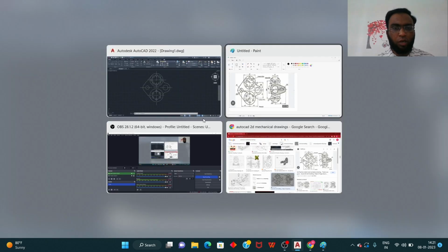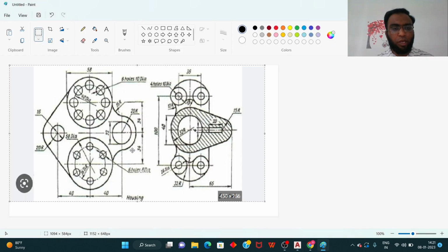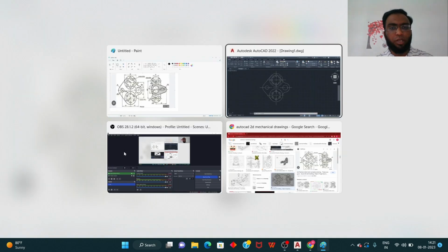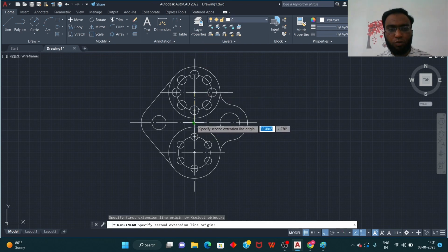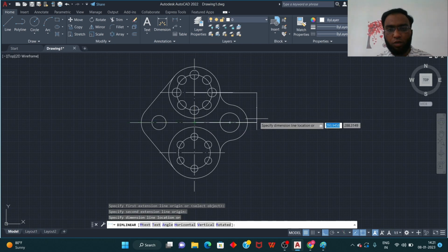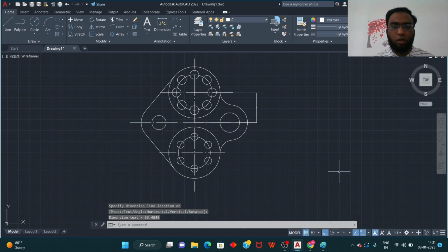And now coming to the dimensioning. So definitely you can, first of all, check it out. So linear dimensions. So here 58 is a linear dimension and 40 will be a linear dimension, 34 are linear dimensions. Okay, apart from that, 22. So these are the linear dimensions. And now, apart from this, the remaining are the diametrical and the radius dimensions. Okay, so first let us go for this linear dimension, linear. So the linear will be from this distance, from this center to this one. So you're going to have the linear dimension for this. Okay, so now you can observe.